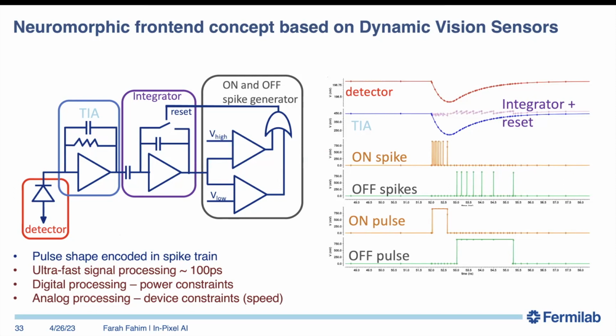So if I just take a model, like a VCVS kind of a source without putting a transistor circuit together, you can see this time frame here. It's 4 nanoseconds from start of the waveform to the end of the waveform. So essentially, you're producing these spikes at a few hundreds of picoseconds.